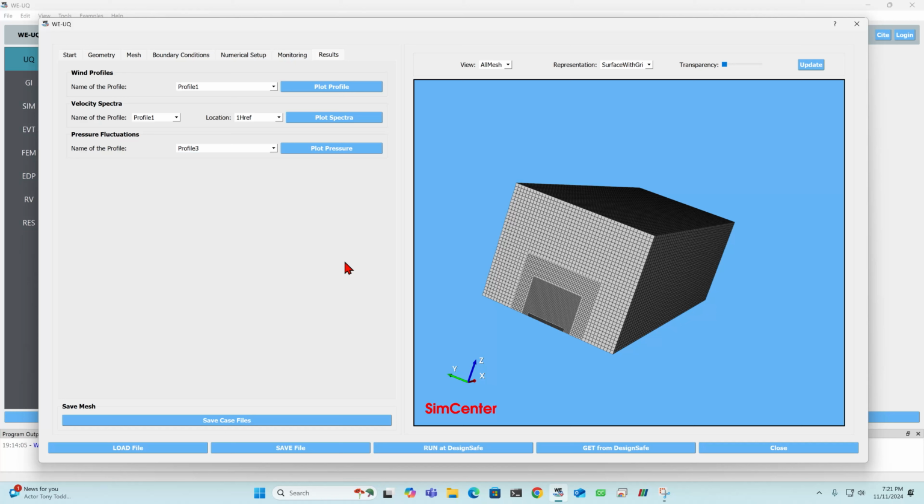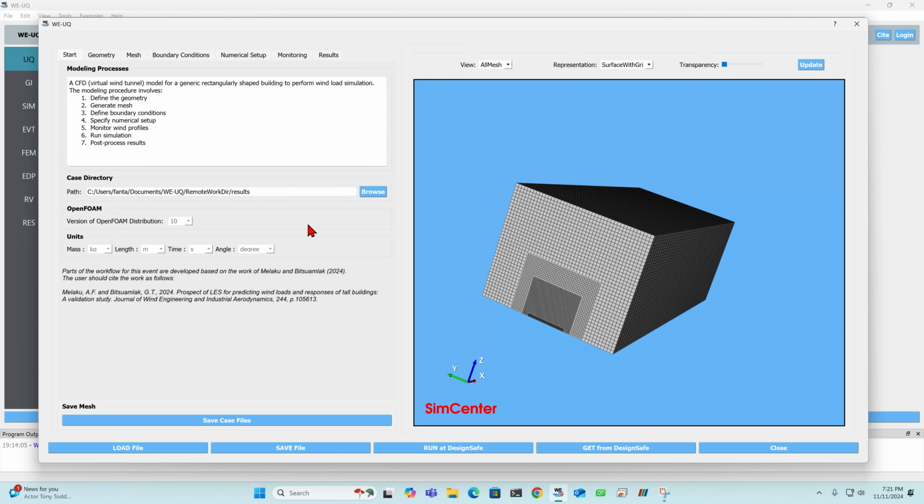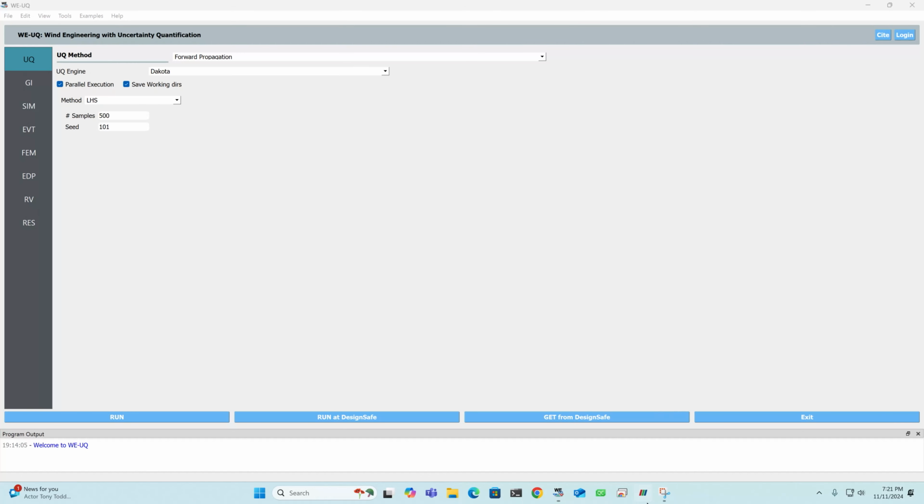Now let's look into the flow field data. When you download your simulation results from the server, it will save them into the default directory, which is located in your documents folder. This is the path where the results are saved. Let's copy this one, and we will look into this directory and see how we can load this simulation data into a third-party software called ParaView and look into the flow field. So let's copy this here, close the window and open ParaView.